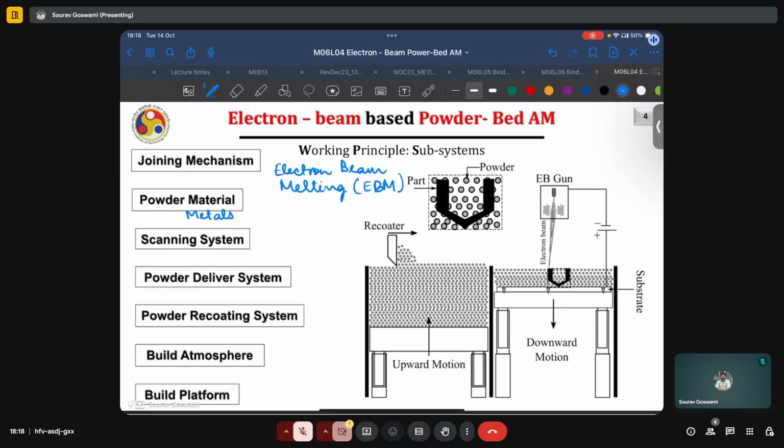It may also be quantified in other terms, such as by just using the height instead of areas. And depending on the formulation you're choosing, it will give you some extent of dilution. Typically, dilution between 10 to 40% is recommended for metallic systems to ensure sound metallurgical properties and healthy mechanical properties of the built part.